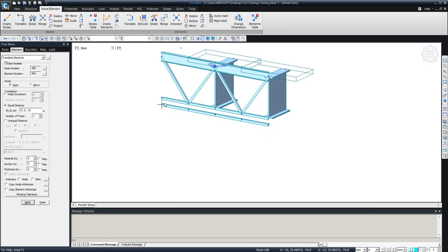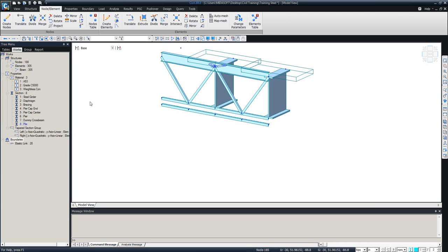This time I'm using these bottom elements just as a tool. I want to just use them to create my abutment, and then later on it will automatically be removed. I'm not going to use this as a structural element. So you see how it works.